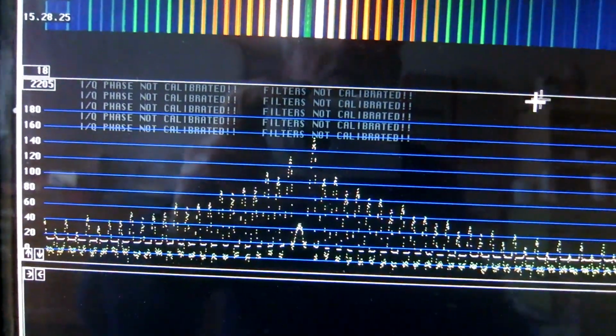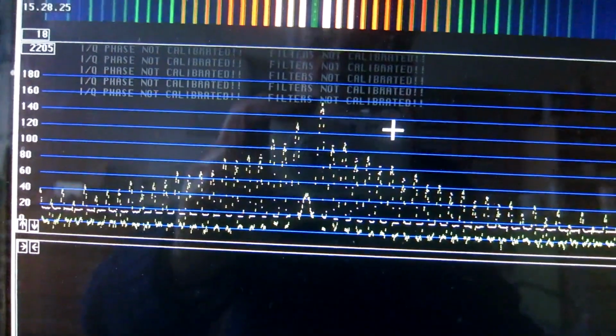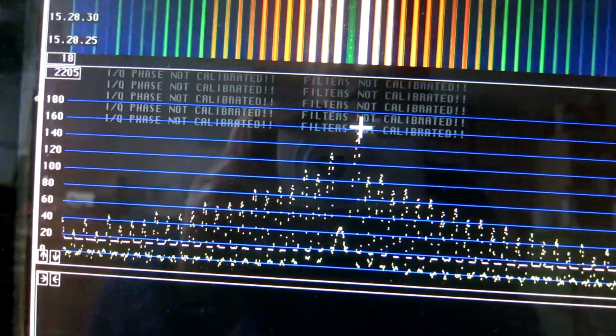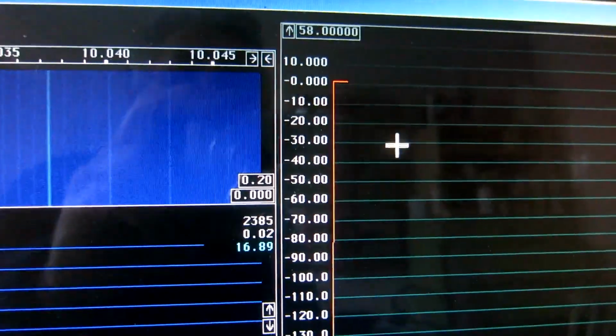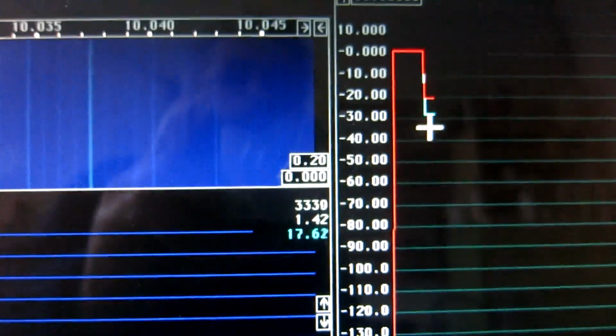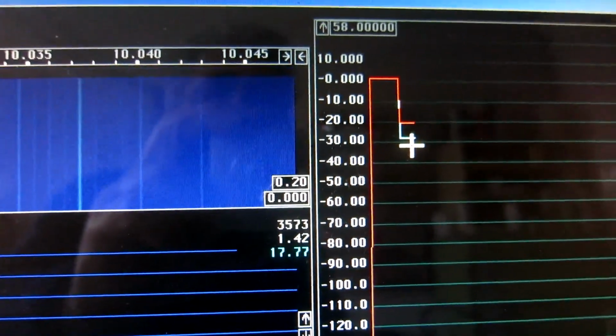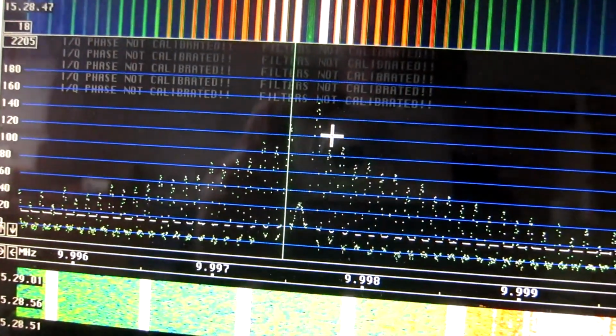It doesn't look so nice, but it's a little bit misleading because the peak here is calibrated to show 0, roughly, on the S-meter graph. The second biggest peak here is the mirror image, and it's suppressed by 20 to 30 dB. So energy-wise it's insignificant.